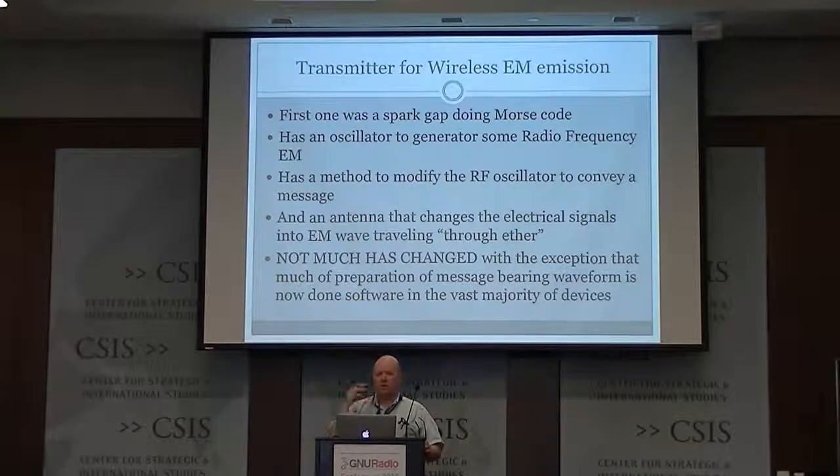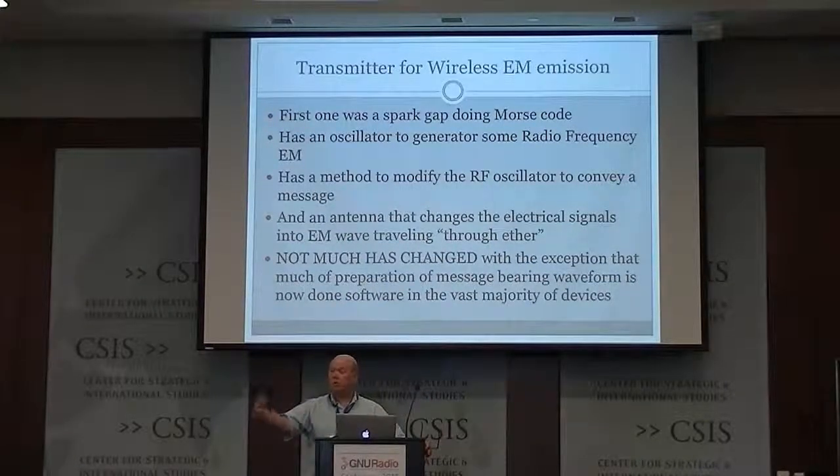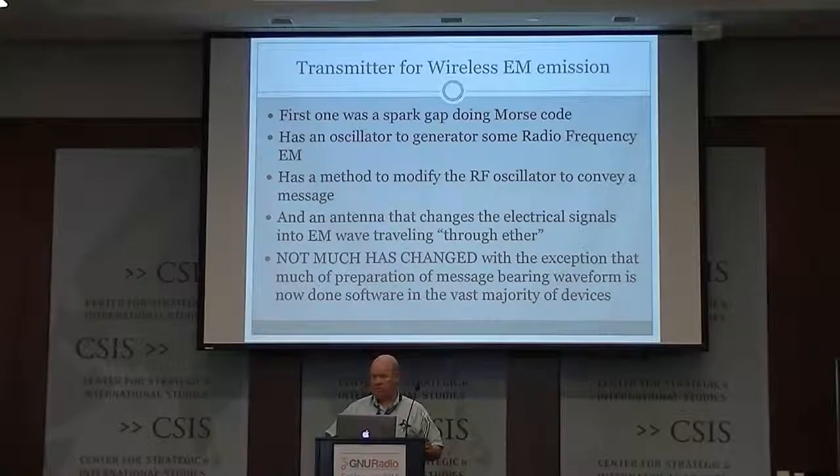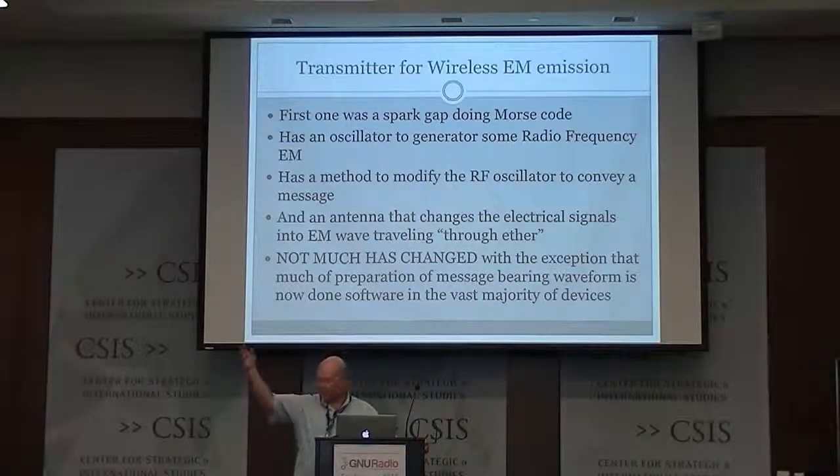So your measure of how good an antenna is doing is if you maximize the power transfer. If I have a sink and I have a source, how do I maximize the power transfer? Match the impedance. That's exactly right. I maximize power transfer when the source and the sink have the same impedance. So you want as much of the sink to be radiation resistance as possible. Now, I don't want it to be a 50 ohm resistor. I want it to actually be radiating. Okay, so I don't want to be turning it into heat. I want to be turning it into electromagnetic waves. So all that stuff goes into the design of an antenna.